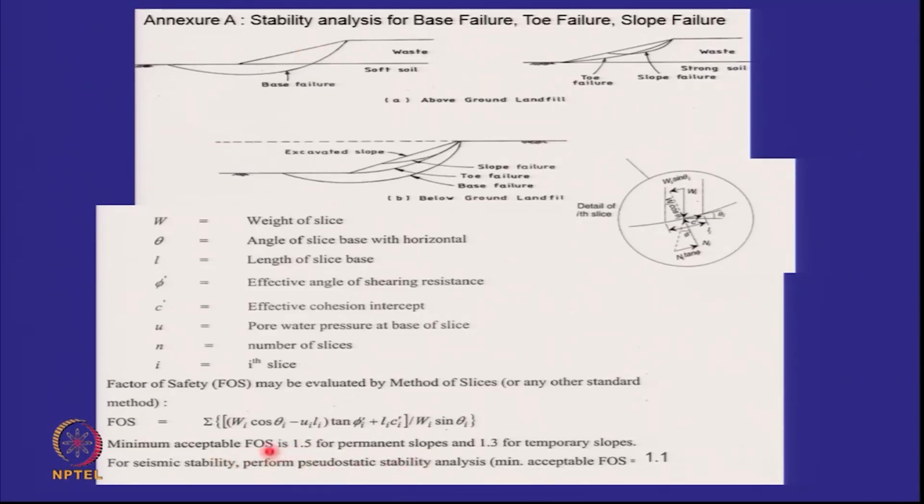There are other conditions for which you will perform stability analysis, typically, for example, for seismic conditions. In the pseudostatic method, you may use a factor of safety of 1.1.